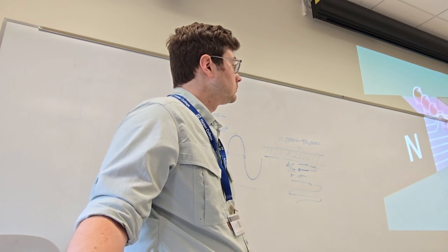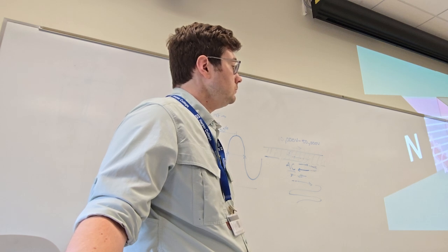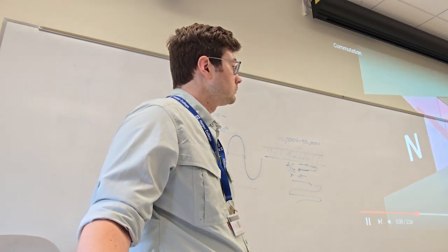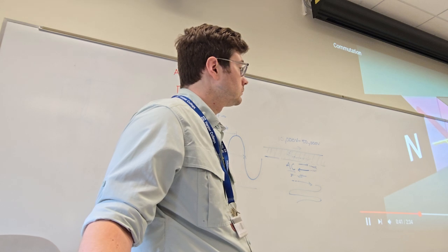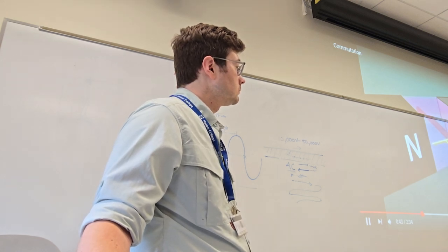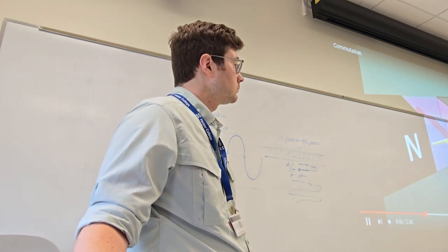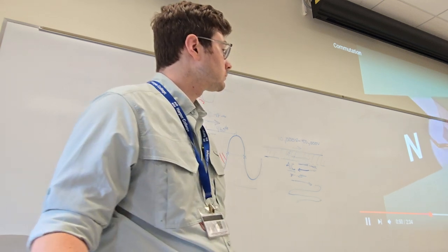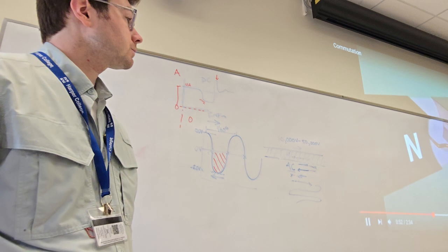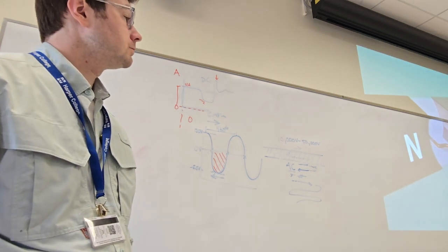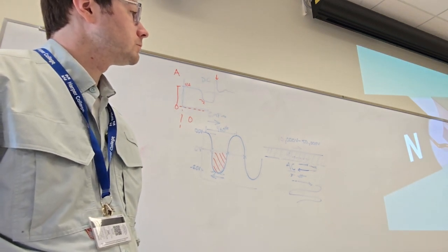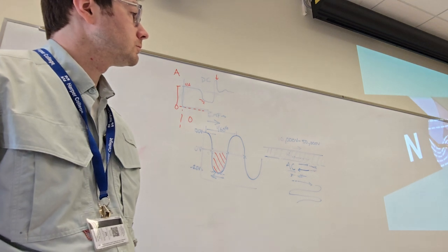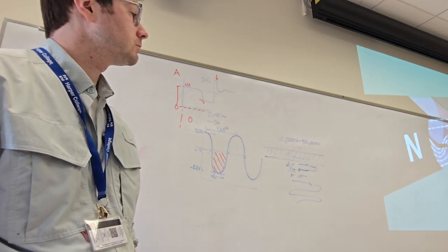Reversing the direction of current flow in the conductor will cause the conductor to move in the opposite direction. This is known as the motor effect, and is greatest when the current carrying conductor and the stationary magnetic field are at right angles to each other. A conductor loop, which can freely rotate within the magnetic field, is the most efficient design. In this position, when current flows through the loop, the stationary magnetic field is distorted and the lines of force try to straighten.